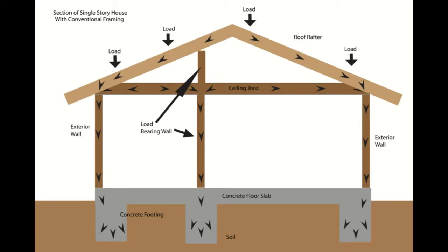Now here's something else you could run into, and that would be a load-bearing wall with another wall on top of it in the attic, let's say, supporting the roof. And here would be something where it would be supporting the peak of the roof, or the ridge, with some type of a bracing system. And if you had something like this, you poked your head up in the attic and you see this, there's a good chance you won't be able to remove the wall.